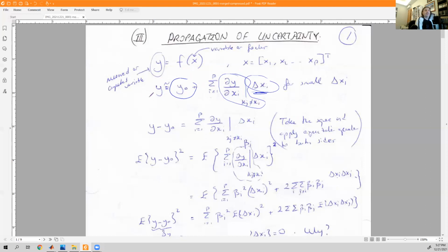This is an approximation, as the actual Taylor's expansion consists of an infinite number of polynomial terms, and the logic is you can write any function using this infinite number of polynomial terms. But this works if we have a very small delta x value, so a very small perturbation of x around their equilibrium points or measured points. How are we guaranteed this is going to work for our case? Because we assume that uncertainty in the measured variables is small compared to the actual values of the variables. So we hope that this assumption would work. At least we are going to cover the cases for which this assumption will be valid.